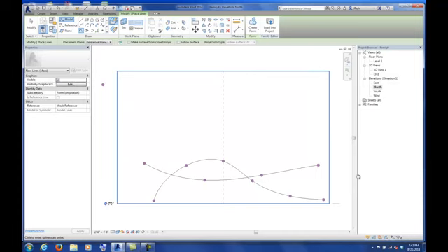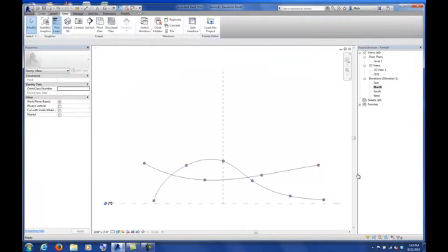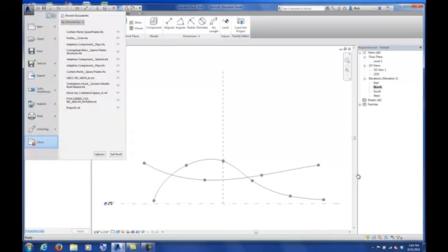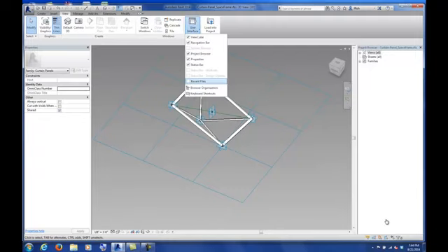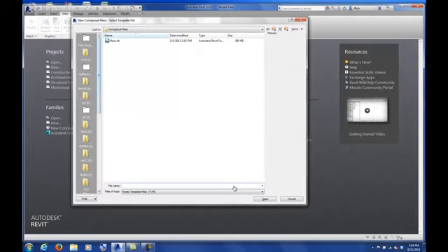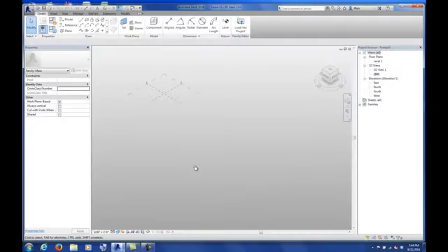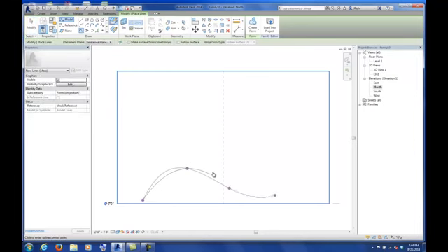Yes? Did you open a family type file or architecture? Yep. So if I go back, I'll just close out of this. Looks like everyone got lost somewhere. So from here, we hit save. We saved this guy. I'm going to go to View, User Interface, Recent Files. I'm going to click on New Conceptual Mass under Family, and hit Mass and Open. So now I'm also going to go to the north elevation, and let's go to spline through points and just create some kind of spline. And I'm going to create another one.